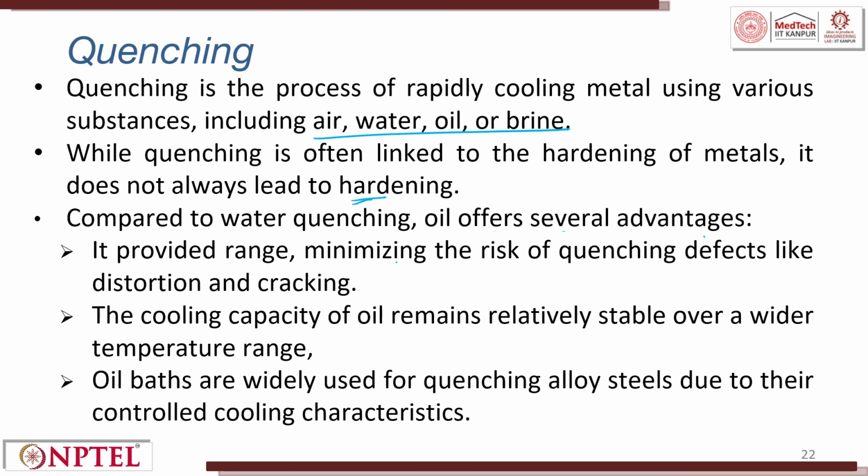It provides a controlled range, minimizing the risk of quenching defects like distortion and cracking. In oil, it is reduced. The cooling capacity of oil remains relatively stable over a wide range. Oil baths are widely used for quenching alloy steel due to their controlled cooling characteristic.